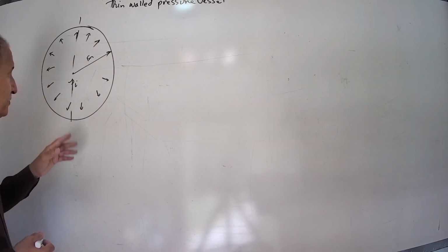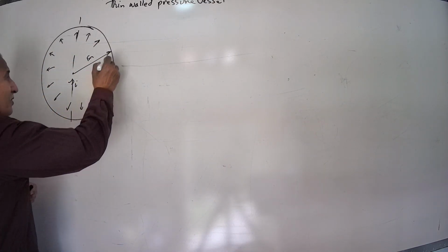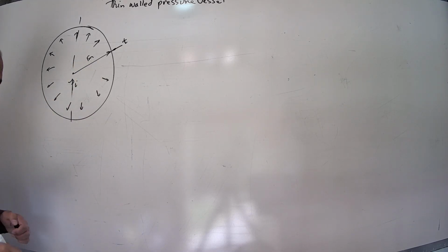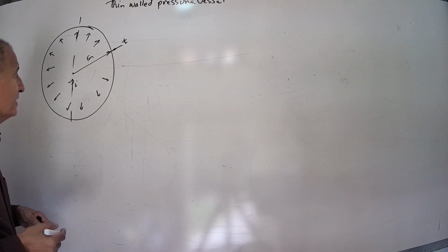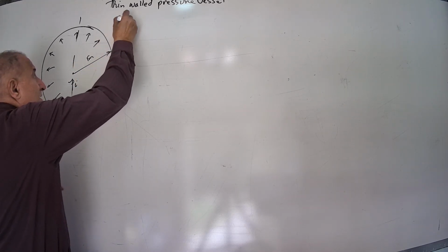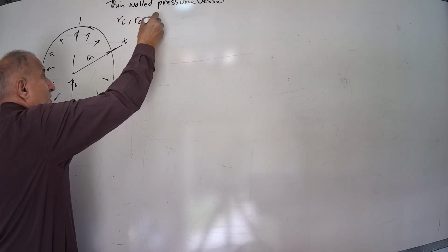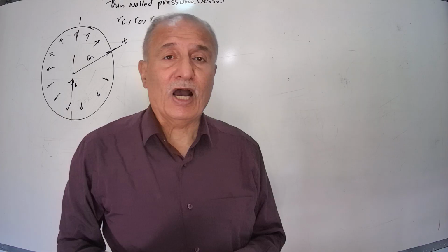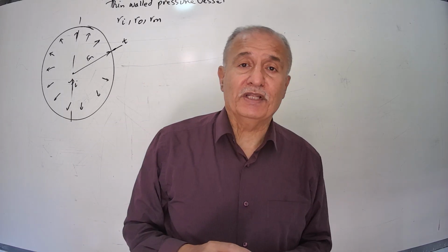Let's consider a thin wall cylinder. Thickness is called t. We consider the mean radius, the average radius. We have R_i, R_o, and R_m here, and later we will see that the standard uses only the outside diameter or outside radius, and we will say why.